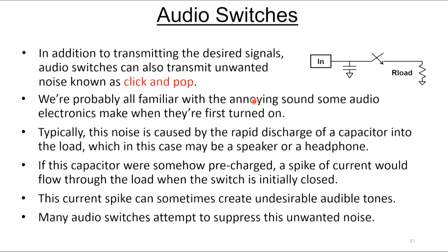In addition to transmitting desired signals, switches can also transmit unwanted noise known as click and pop. We're probably all familiar with the annoying sound some audio electronics make when you first turn them on. You get this very rapid sounding pop in your ear. Typically, this noise is caused by a rapid discharge of a capacitor into a load, as I showed in this diagram over here. Especially if this capacitor gets pre-charged, that spike of current can be pretty hefty, flowing right into a speaker, and you're going to hear it.